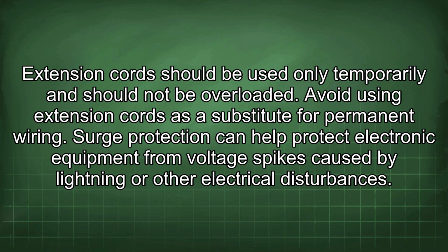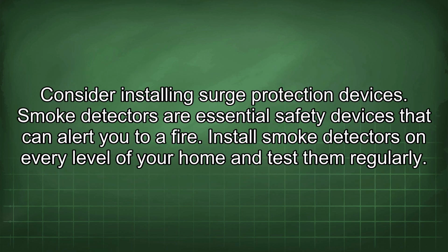Extension cords should be used only temporarily and should not be overloaded. Avoid using extension cords as a substitute for permanent wiring. Surge protection can help protect electronic equipment from voltage spikes caused by lightning or other electrical disturbances. Consider installing surge protection devices.